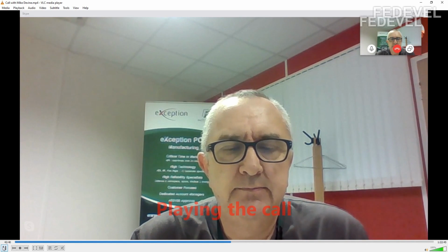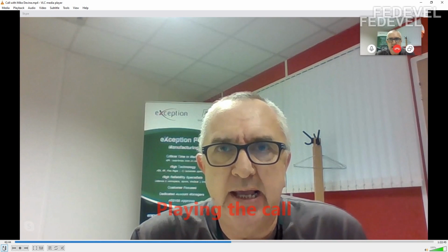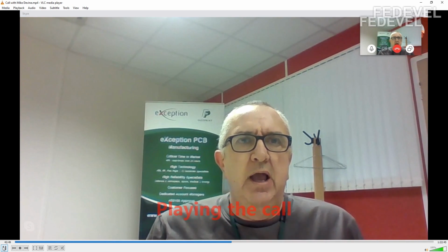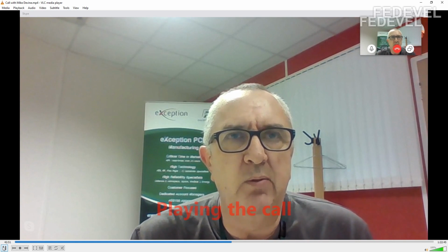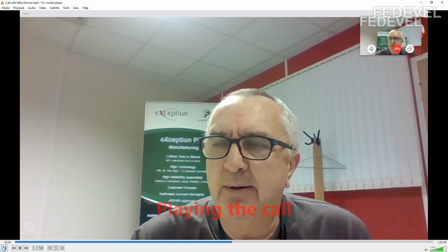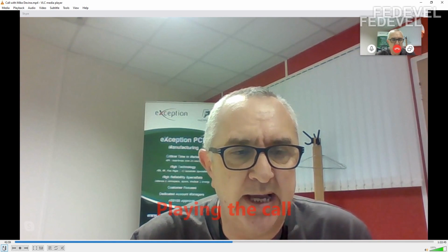It means you put thicker solder mask? In essence, yeah, it is a solder mask resin that goes on, and we apply that through a screen. Our application will fill the via probably around about 60% of the hole.